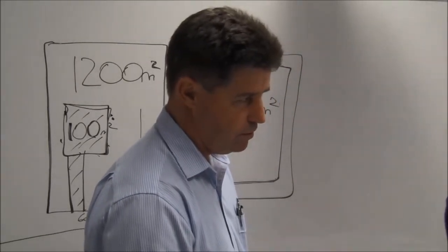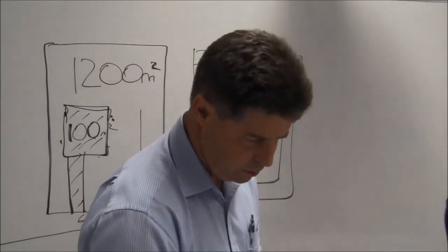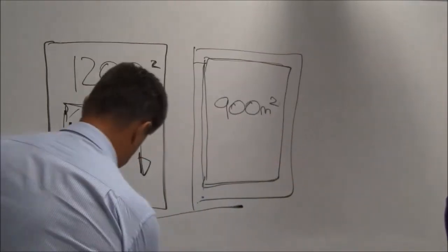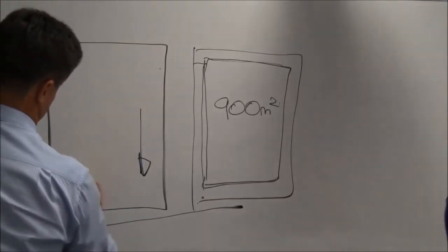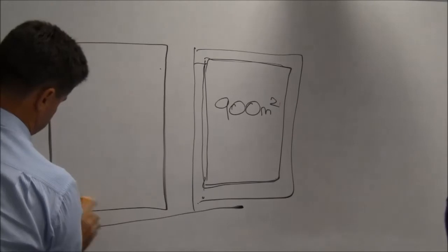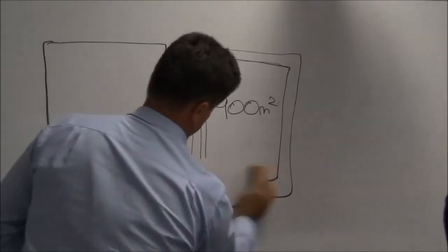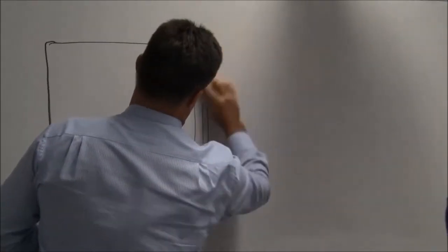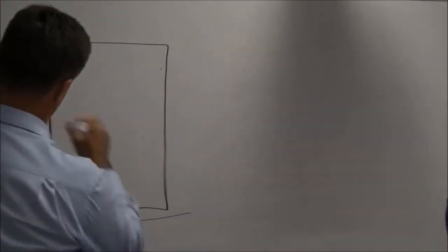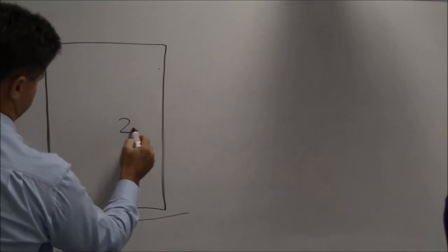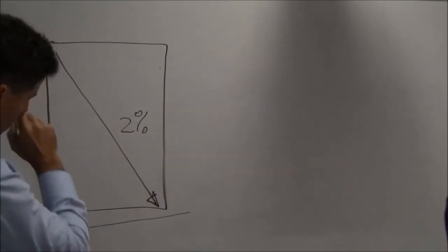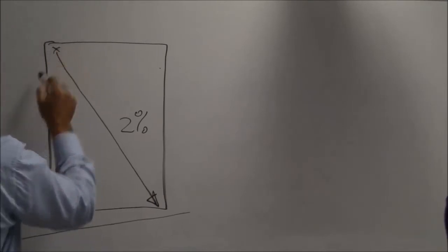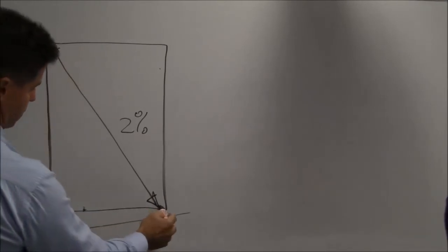What else? Probably the next one then, the time of concentration. We'll use our same site. Time of concentration is just a value from the time it takes for, if we had a site at a 2% fall, falling somewhere across there, it's the time it takes for water to land at a point and get to its discharge point.